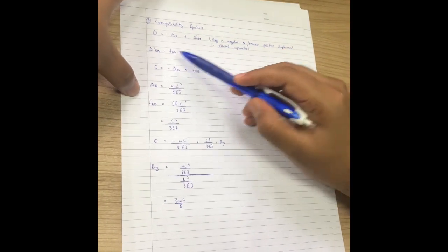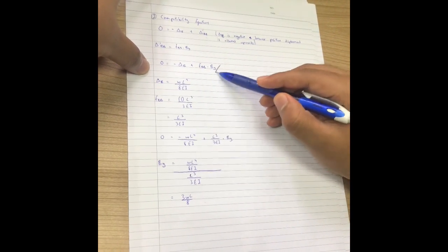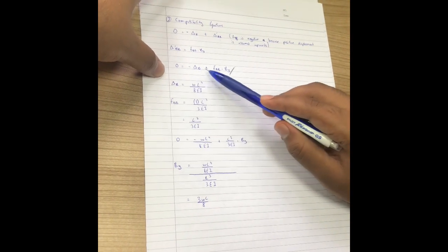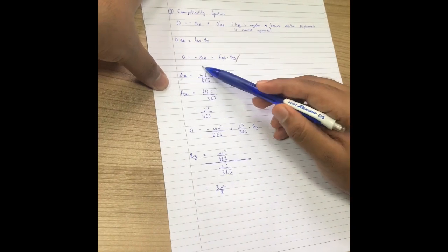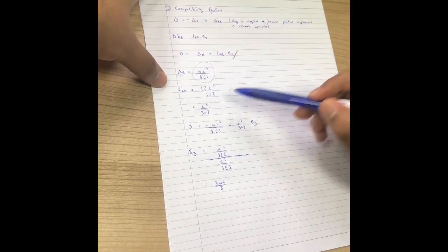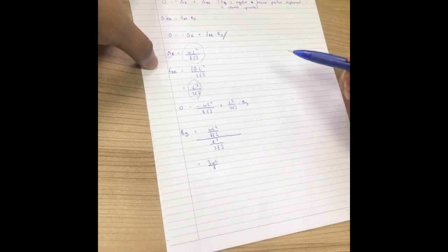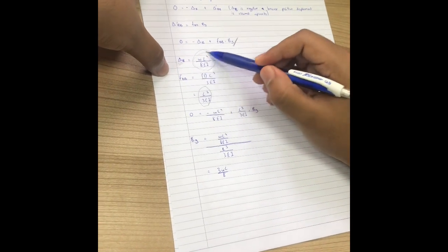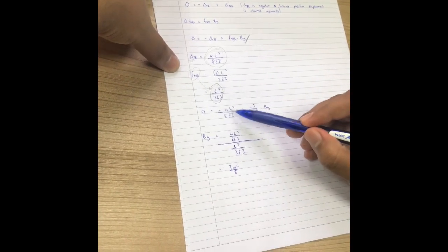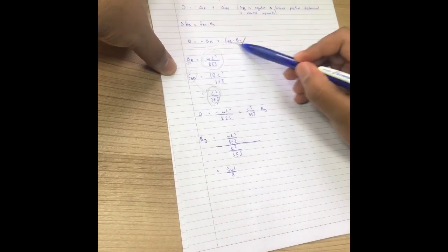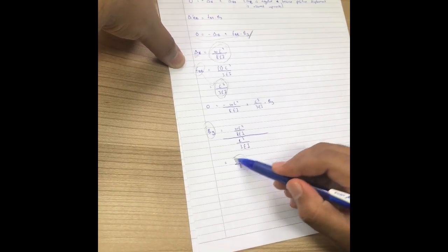Okay, and we know delta prime BB is equals to FBB times BY. So this is our actual compatibility equation. It's negative delta B plus FBB times BY. To find delta B, we know this formula you can get from the table. Then we just plug in the values. We can get delta B, and we can get our flexibility coefficient, which is this one. Then we plug in the value into this compatibility equation to get our BY. This is our BY value now.